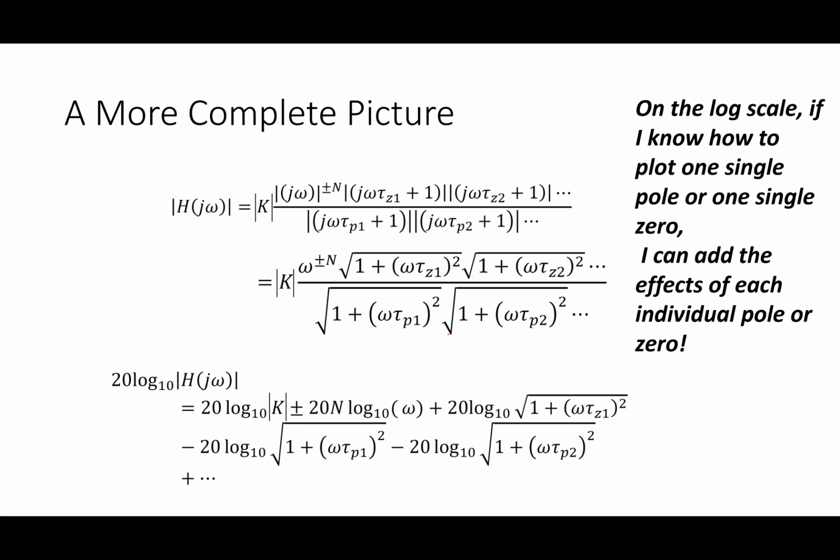There's this one here, 20 log of a constant. Now, notice one thing I do here. When I took the magnitude of this whole thing, K is a constant. I probably give you some in the homework where K is like -10, right? -10 is not a magnitude. What's the magnitude of -10? 10. -10 is a complex number, which if I wrote in polar form is 10 angle 180, right? So that has a 180-degree shift. When I take its magnitude, it becomes just 10.